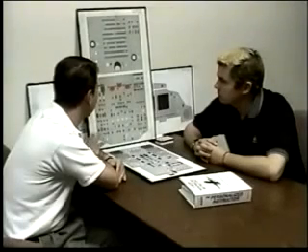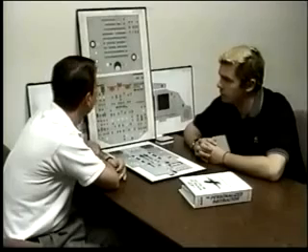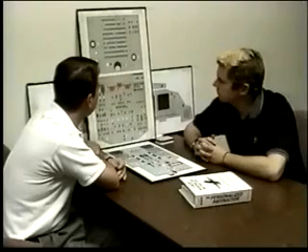Since low level, did the center tank pumps shut off right away? No, they'll continue to run for 5 minutes. After 5 minutes, they shut down. You're burning your inner wing tank fuel.